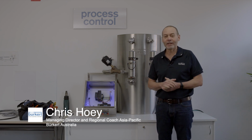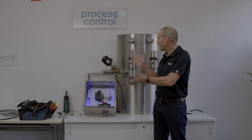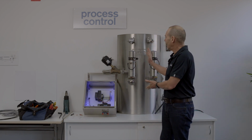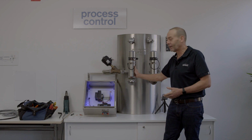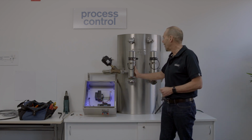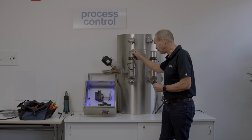Hi, I'm Chris Hoey. We've spoken a lot about digital connectivity, but today we're going to showcase how we can actually put that into play. What we've set up here is a generic wine tank application. On the left-hand side, we've gone for traditional wiring, so an RTD, a brine valve, and of course a butterfly valve, which could be used for pump in, pump out, etc. On this valve, we've also got feedbacks for pump safety and the like.